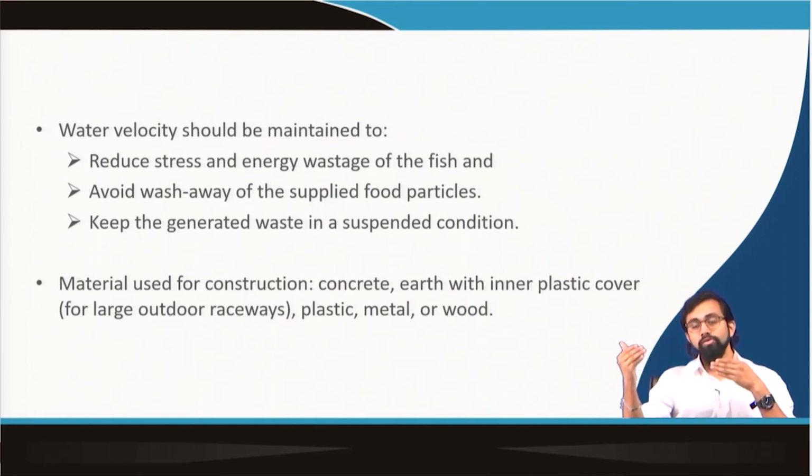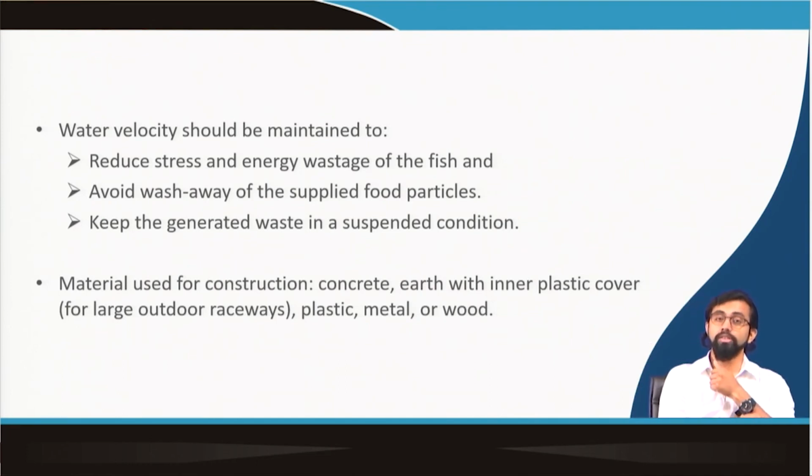Which will consume more energy, do you think? It's definitely the one which keeps pausing at regular intervals, because starting the engine requires a lot of energy. It's the same way with water velocity. If you have a continuous flow of water, it will cost you less energy than if you keep starting the pump and stopping it, and again starting and stopping it. It will consume a huge amount of energy. It will also cause a lot of stress in your fish because of the lower dissolved oxygen present in your system.